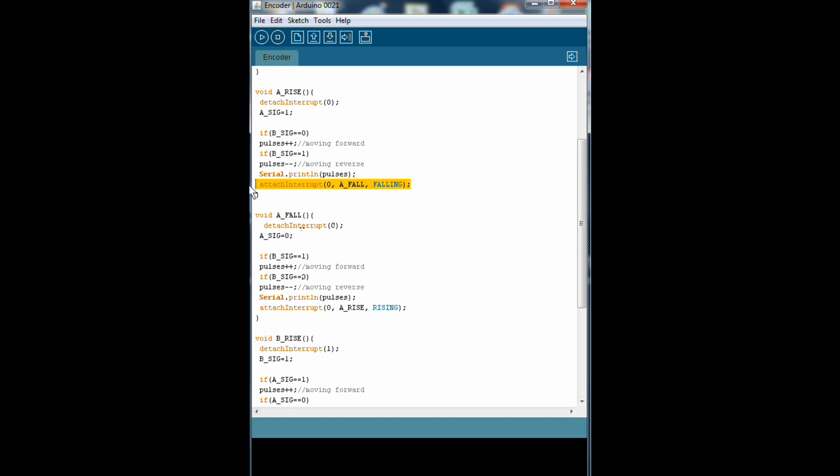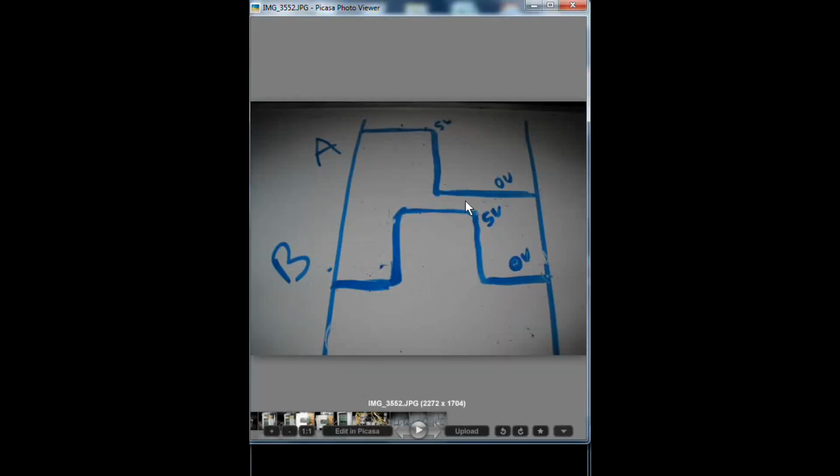The reason I do this, and it's very important, I think, in the code, and in my opinion the only way that makes sense, is that if you miss a pulse and you simply detect a change in state from either high to low or low to high, you have to trust your code that you'll catch each pulse. If you miss a pulse and you don't detect it, then there's a good chance that your counts will actually switch directions on you, which you don't want.